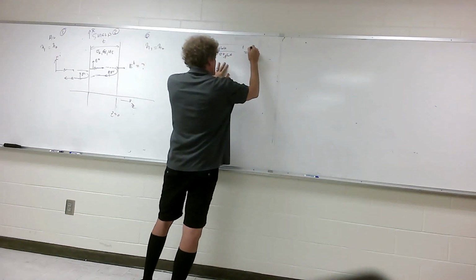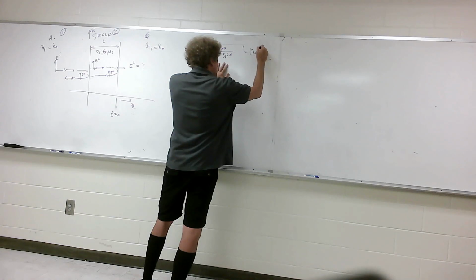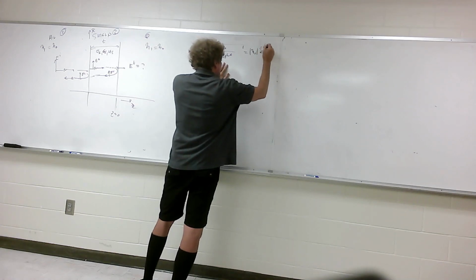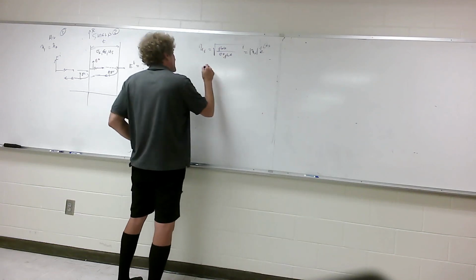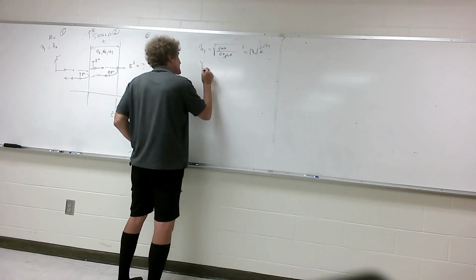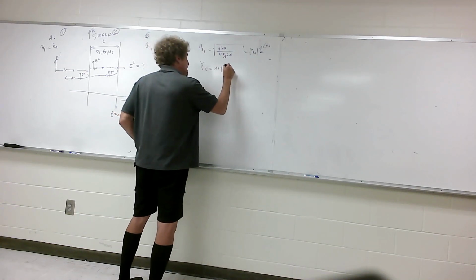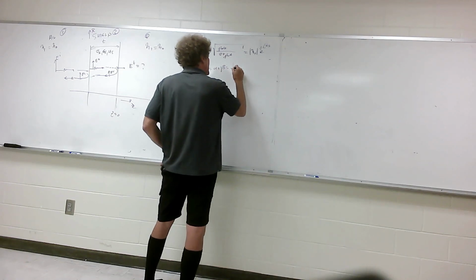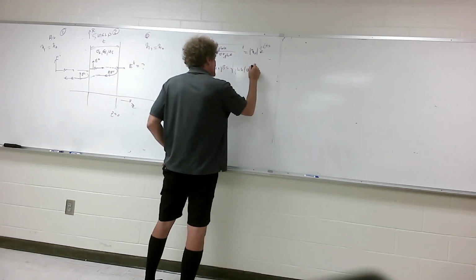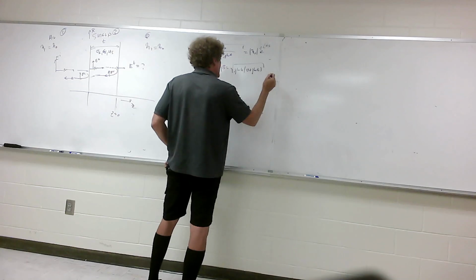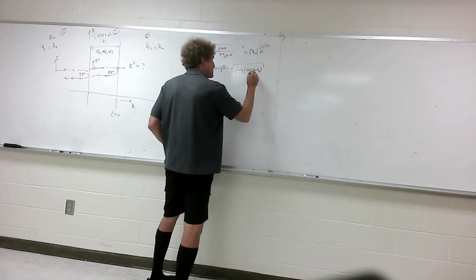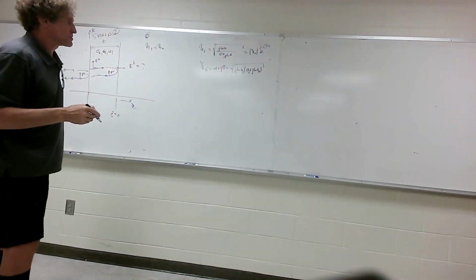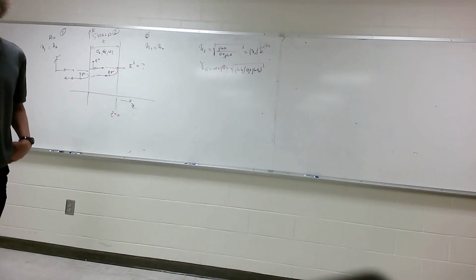That's going to have a magnitude of eta shield, and it'll be at an angle, probably 45 degrees if it's a decent shield. And then you're going to have to get the propagation constant in the shield, which will be alpha plus j beta, and that's the square root of j omega mu times sigma plus j omega epsilon in the shield. I'm trying to make sure you understand these are all constants or values associated with the shield. You all with me? Everyone?